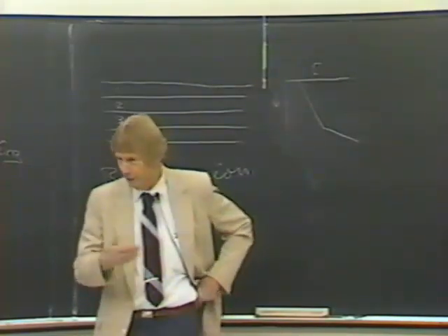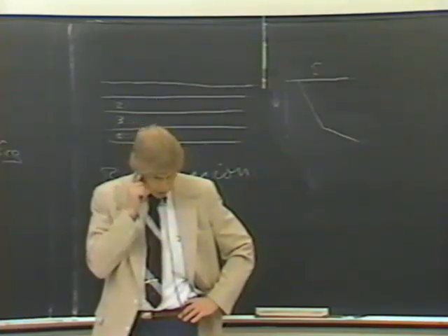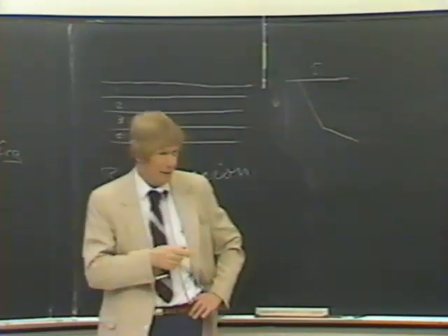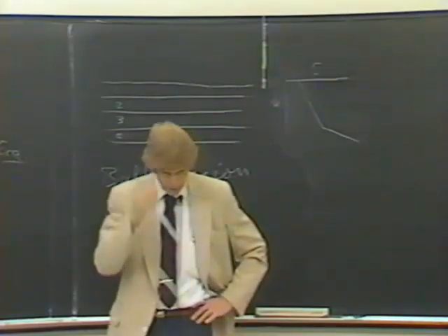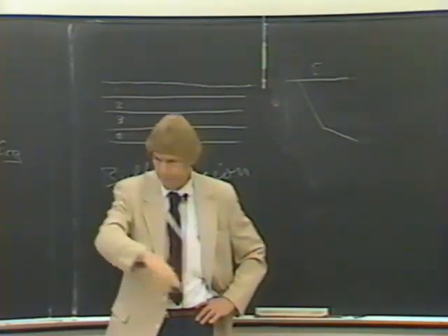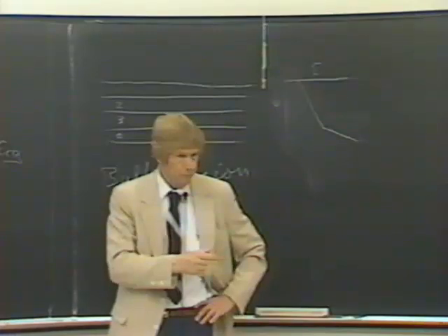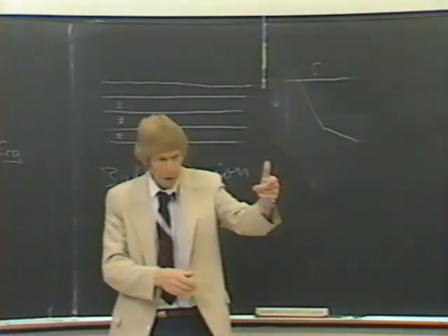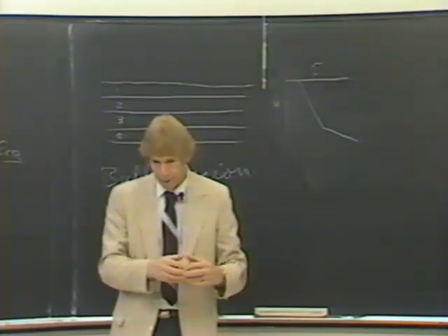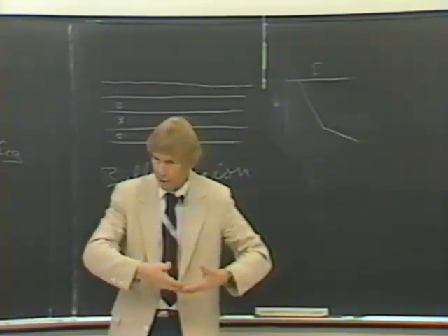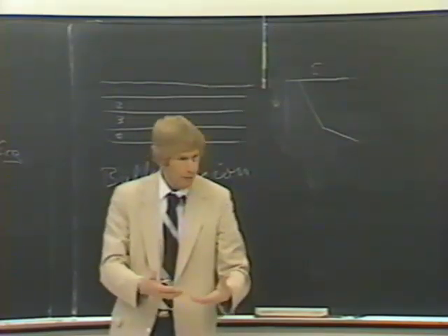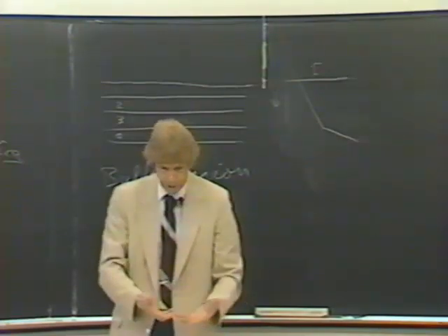The main cause of bridge failure is scour of the foundation. So we approached the model. This was 1975, where modeling wasn't nearly as advanced as it is now. But the approach, I think, would be the same. We approached this problem by, first of all, constructing a model of the flows around the pylon. Secondly, we had samples of the mud flown up, and we used that rotating cylinder apparatus I described to determine the critical shear strength for erosion of the mud. And that gave us a boundary, it would erode until the bed shear stress equaled the shear strength of that material. You can put a safety factor on top of that, but essentially that was the method.